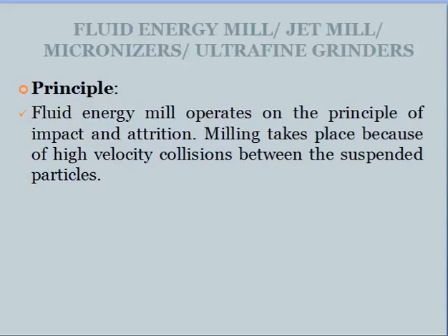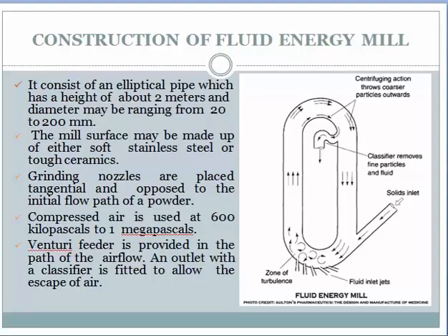Now we'll talk about fluid energy mill. It is also referred to as jet mill, micronizer, also ultra fine grinders. Fluid energy mill operates on the principle of impact and attrition. Milling takes place because of high velocity collision between the suspended particles. We'll see about its construction and working.